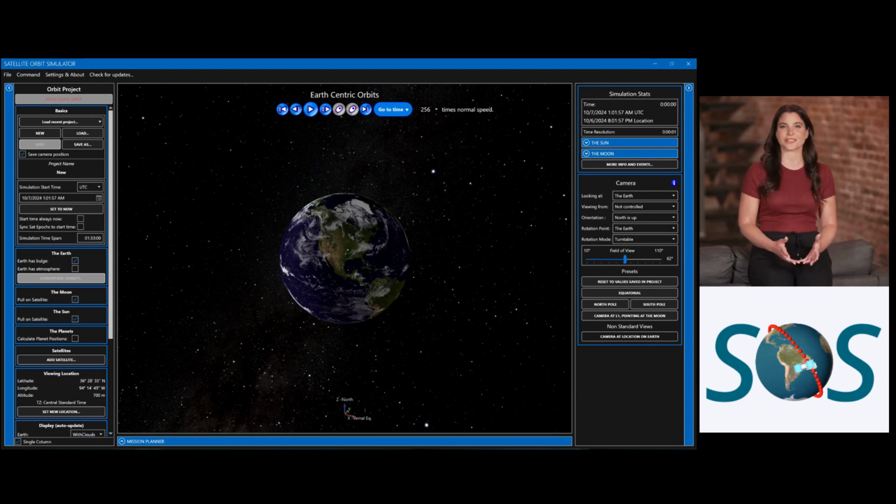Today I'll show you how to design your own satellite orbit using traditional orbital elements. These 6 parameters define orbits in inertial space relative to the ECI coordinate system. When an epoch is associated with these elements, they also define how that orbit relates to Earth's current rotation angle. These are essentially the same as state vectors, but have an older format that allows you to more easily visualize the orbit when simulation software is not available.